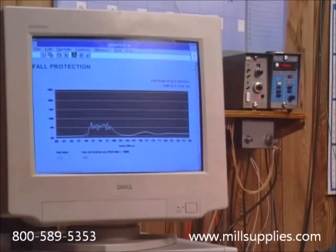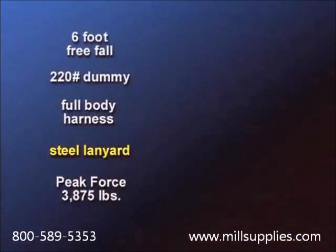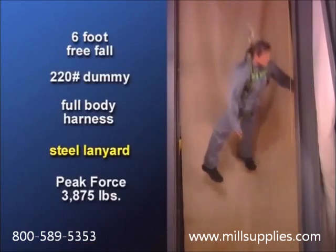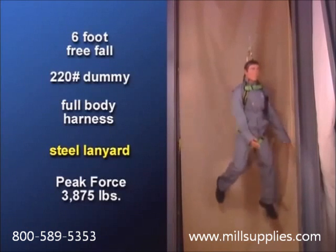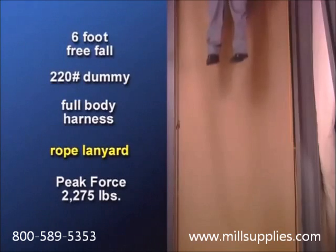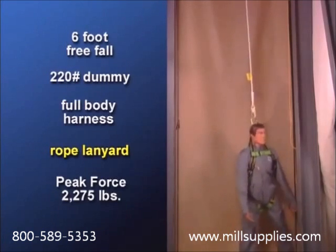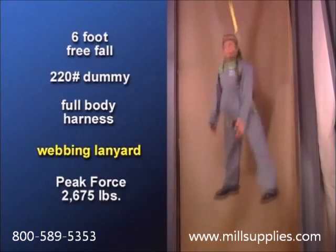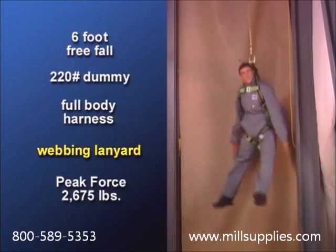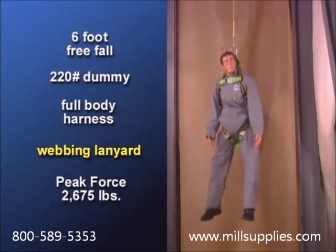This testing apparatus is used to measure the energy generated by a fall. Let's look at the force generated by a 220-pound dummy falling 6 feet. Here the drop test is performed on a steel lanyard. Note the head snap and bouncing of the dummy. Forces are well over 3,000 pounds. Now, a rope lanyard. And a web lanyard, both with forces over 2,000 pounds. In each case, the extreme forces generated caused head snap and bouncing of the dummy.